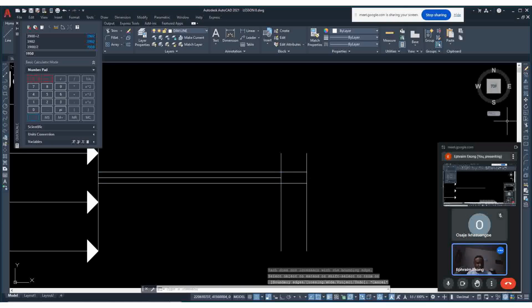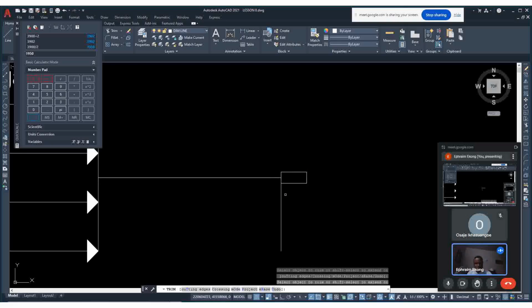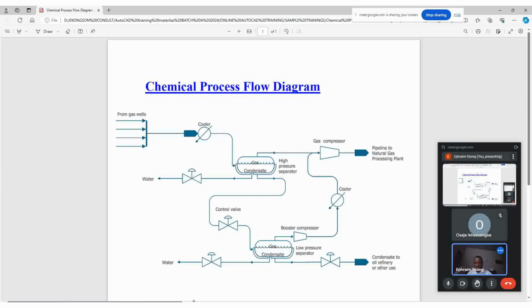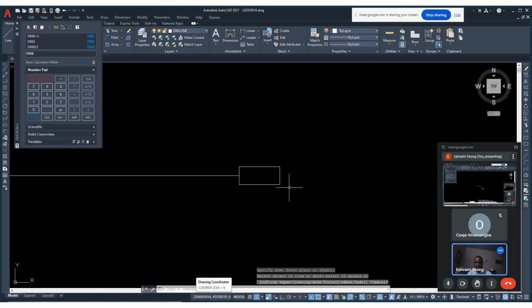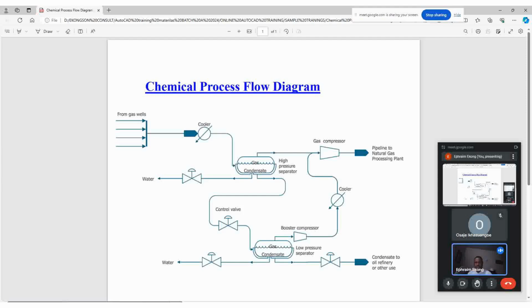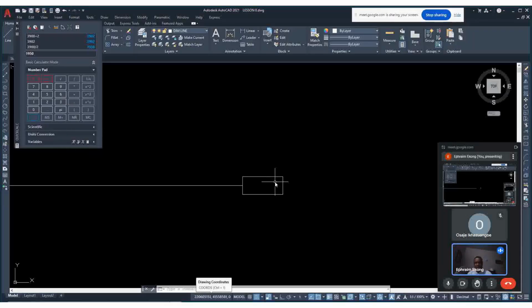Okay, then we click on trim and press enter. So the idea is to get these centralized parts. Okay, so you trim off, trim off, trim off. So you have gotten something like this. Okay, so what next is, I think it's a bit fatter than this. So we could extend like 100, 100. We choose 150, 150. So we can extend 70, 70. Click on offset. Sorry, offset. You type 70 and press enter.